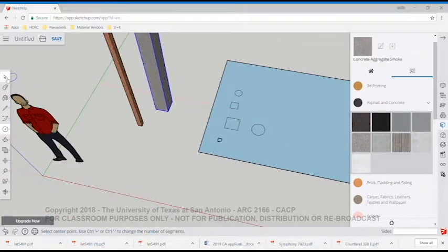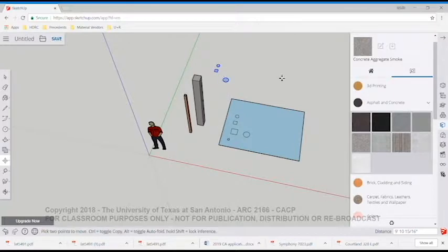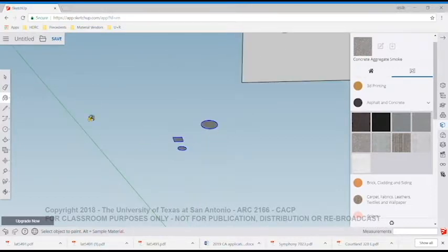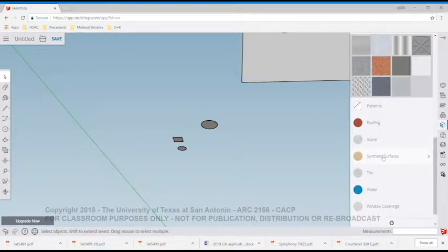So there's 3 pieces, and let's just go ahead and do all 3 of these at one time. I'll use the Control key on the Select tool, and then I'll copy those off to the side, and I'll paint them. Both of those are going to be wood, and that one's going to be concrete. I've got the concrete there. Just go ahead and paint both sides. It's painting everything I've selected, but I can just deselect it and get that other bit.